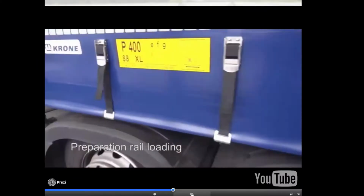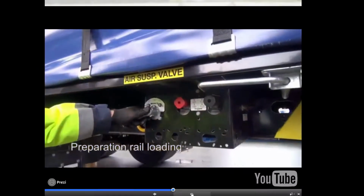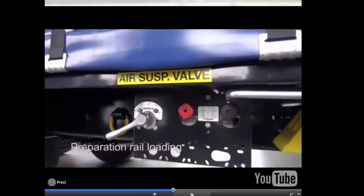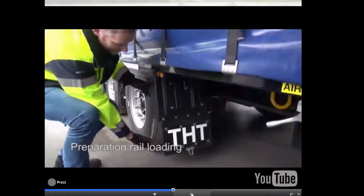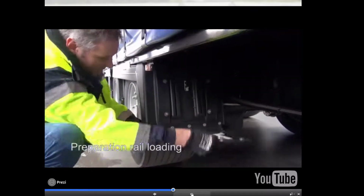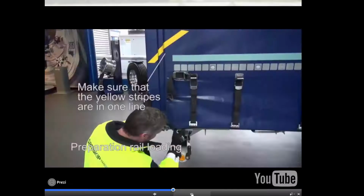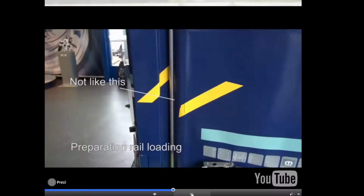When the mega trailer is transported on rail, the trailer needs to be set to the lowest level possible. This is also done with the air suspension system. Also, the mudguards need to be secured. We always need to make sure that the yellow stripes on the sides of the mega trailer are in one line, otherwise the crane may damage the curtain when lifting.